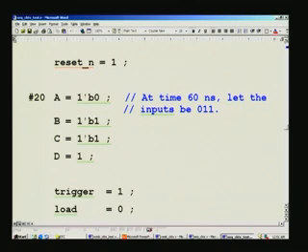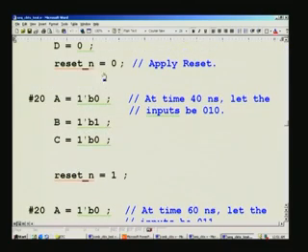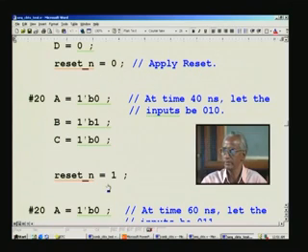So, after that we bring it back to 1 from 0, after 20 nanosecond we bring it back to 1. So, that normal working of the sequential circuit can commence. Only subsequent to this positive edge clock will arrive, only from then onwards its system starts working. So, the whole affair goes within 20-30 nanosecond, right. At 40 nanosecond you can see, subsequent to this clock must arrive. So, it may arrive somewhere in between here, right, around 50 nanosecond.